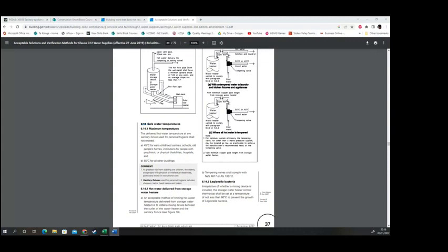It could be the pressure reducing valve has failed. It could be the thermostat is overheating the cylinder. So there's nothing wrong with either of the valves, but it's relieving the pressure because that's the only place it can get out. So if there's generally potentially multiple things, I wouldn't necessarily just put one.